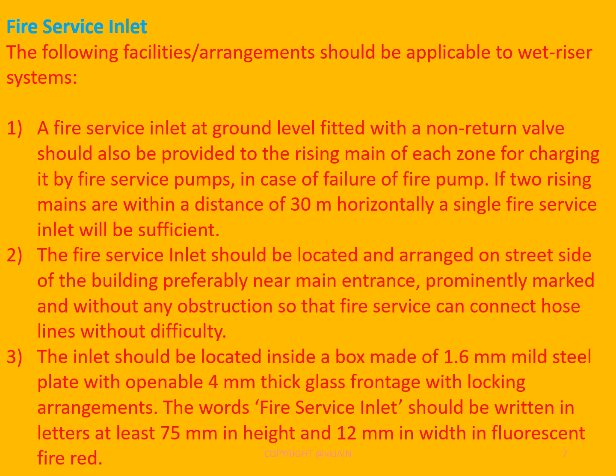Third, the inlet should be located inside a box made of 1.6 mm mild steel plate with openable 4 mm thick glass frontage with locking arrangements. The words 'Fire Service Inlet' should be written in letters at least 75 mm in height and 12 mm in width in fluorescent fire red color.